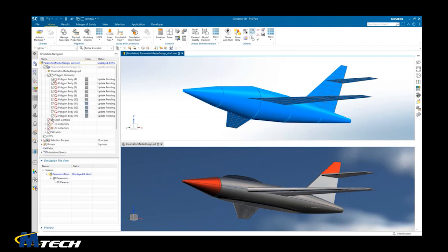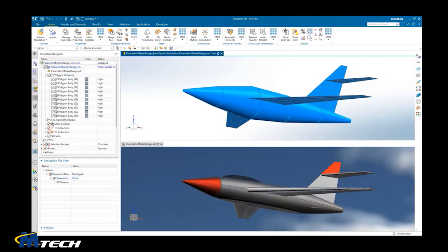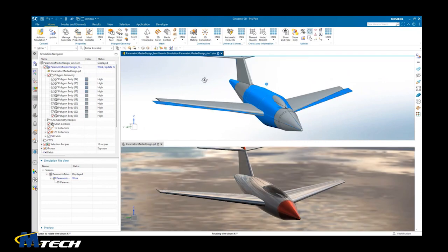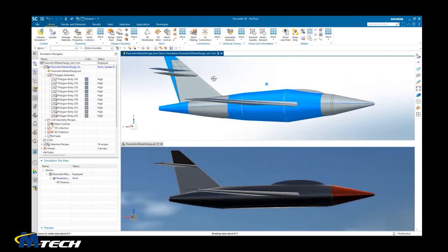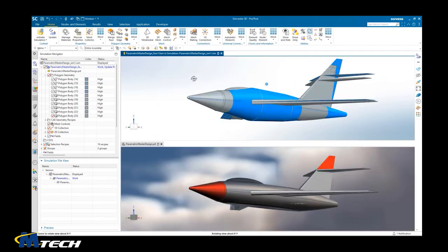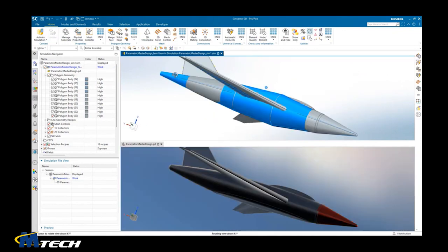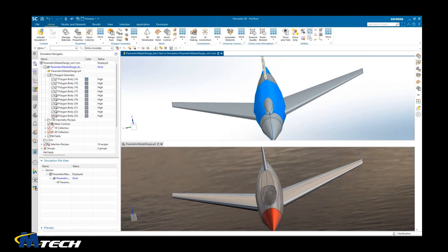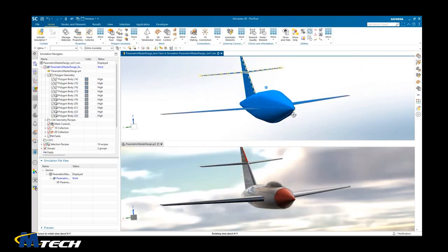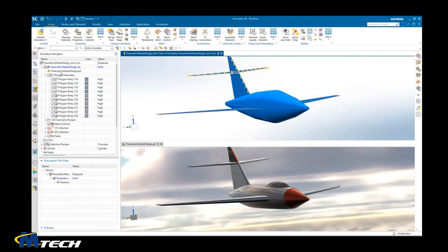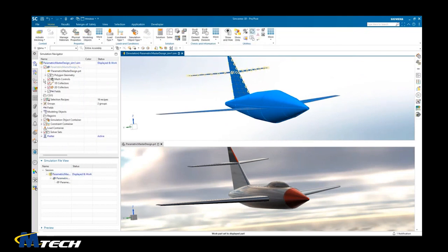Now, the nice thing is when you return to the FE model, we actually see a discrepancy between the geometry and mesh. Now, the update button will automatically sync meshes to align with the CAD update. The whole analysis has been updated because they are fully associative between the structural and aerodynamic model.